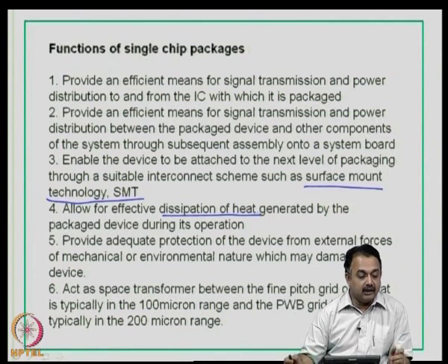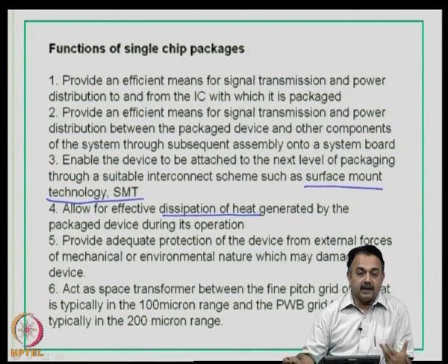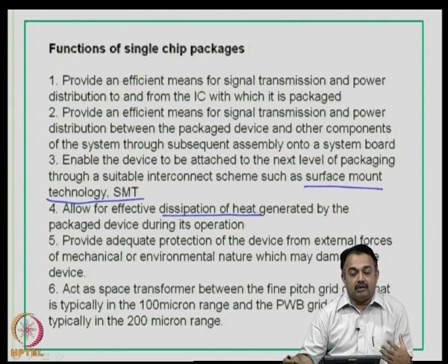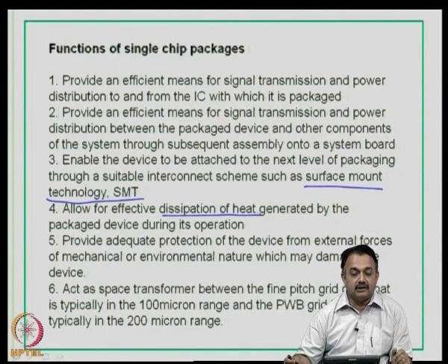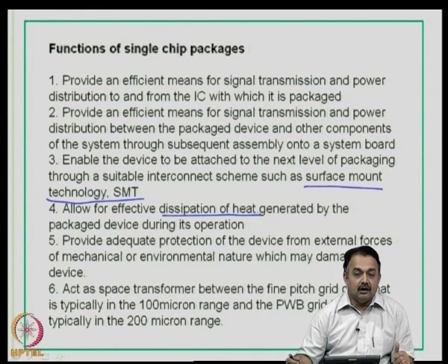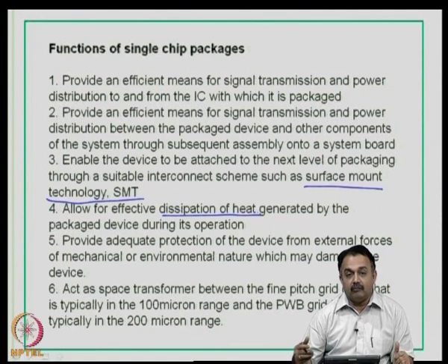So, obviously, when you look at any package, depending upon the size, the package volume also increases. The package volume and the package material, therefore, will have to take care of temperature changes, moisture changes in the particular area of operation of the device, and then dust, and then finally, other electrical or other mechanical interruptions like vibration or a shock and so on.